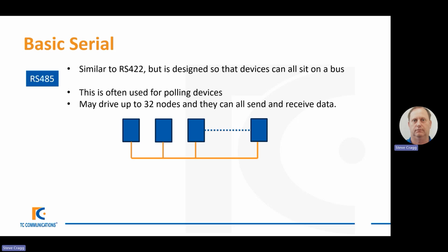But as you can see, in this case, they're using a single bus, so it's half duplex. So one of them will seize control of the bus, will send the data, the others will listen. Once the bus has been given back to its quiescent state, then the other devices may send data themselves.